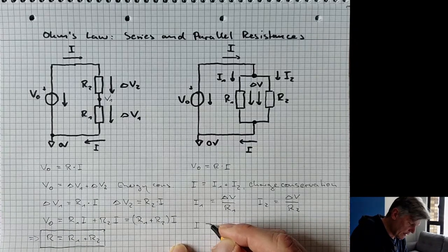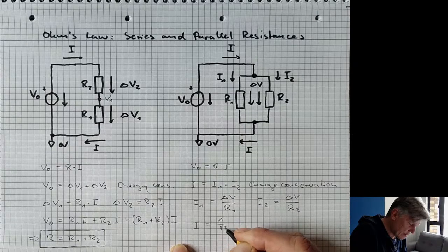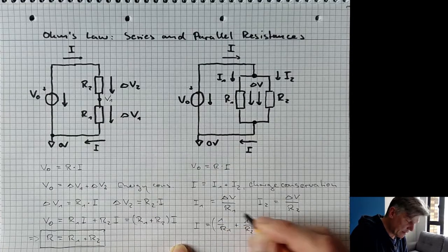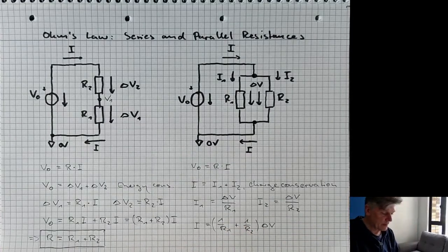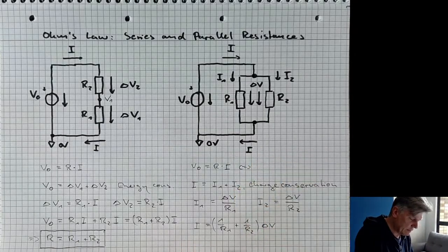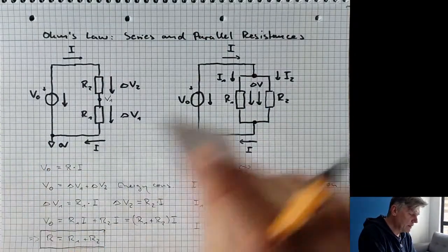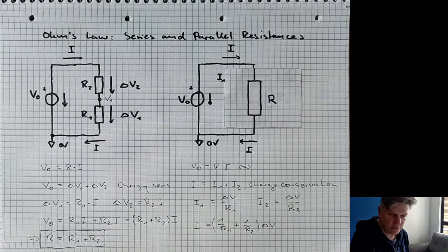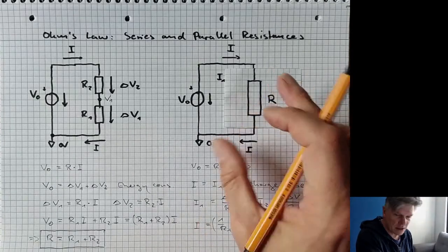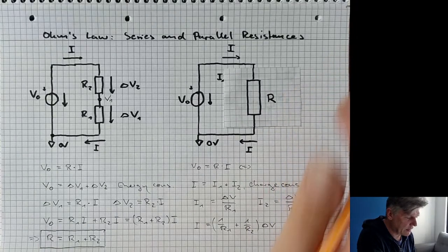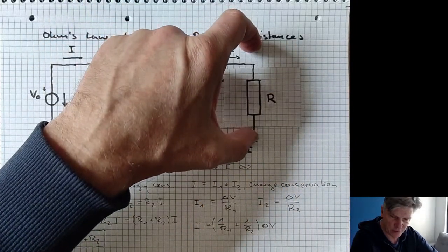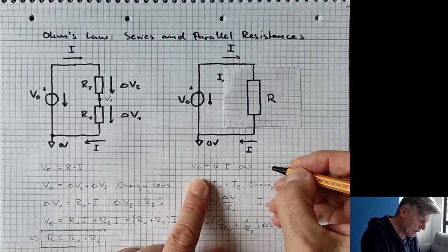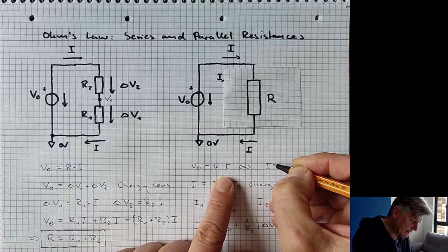So it follows that I is now 1 divided by R1 plus 1 divided by R2, and I'm now factorizing this dV, right? And if you compare this, this is equivalent. If you go to the initial picture, when we observe this thing from outside, we see just this effective resistor. So forget about the internal structure of the resistor, right? What we see from outside is just the current and the voltage drop across this large structure. That's this formula. And let's solve this for I.